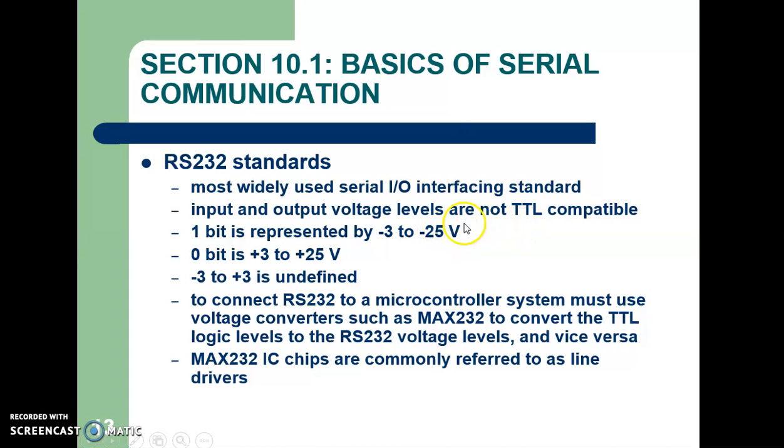If it is not TTL compatible, how do we connect it with TTL ICs and other microprocessors and microcontrollers? We have to use a driver IC. To connect RS-232 to a microcontroller system, we must use voltage converter ICs such as the MAX232, to convert TTL logic to RS-232 levels and RS-232 levels to TTL logic. These ICs are commonly referred to as drivers.